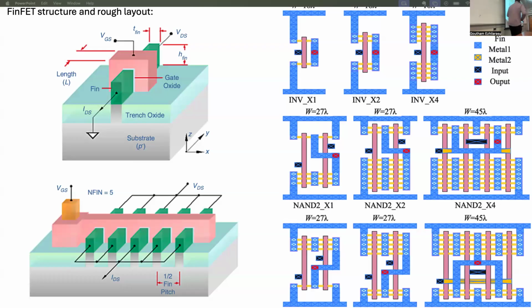Yeah, because the width is basically the part that is conducting the carriers, right? It's basically the inversion layer. So where is the inversion layer forming? It's forming vertically here. It's also forming horizontally on the top, right? In some cases, at the top of the fin there's no inversion channel because it tapers off at the top, so you don't have much space at the top for an inversion layer. But whichever region actually has the channel, that contributes to the width, right? So in this case, if this is basically a rectangle, it will be the 3 sides of this rectangle. So you add this length, plus this length, plus this length, and so on. That's the width of the transistor.